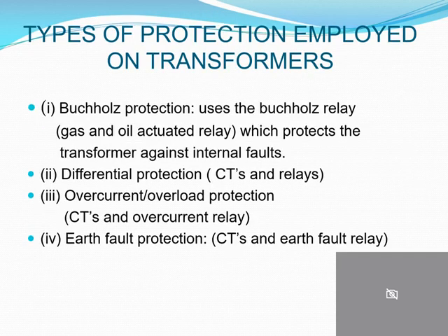For your transformers, we usually have what you call the Buchholz protection, where we have a relay in the transformer that will protect the transformer against internal faults. Then we have differential protection, where we look at whether your current coming in versus your current coming out is the same, obviously taking into account your transformation.